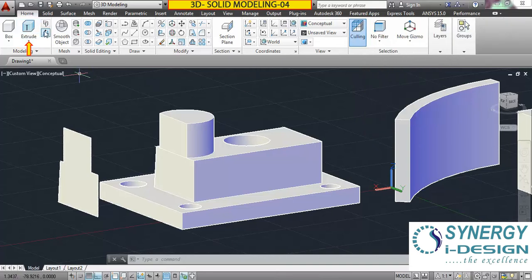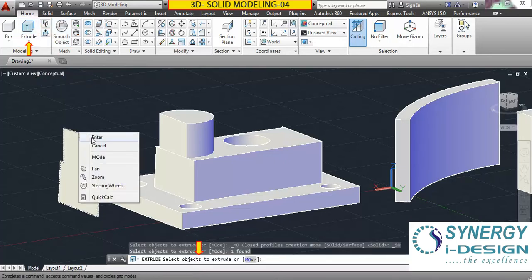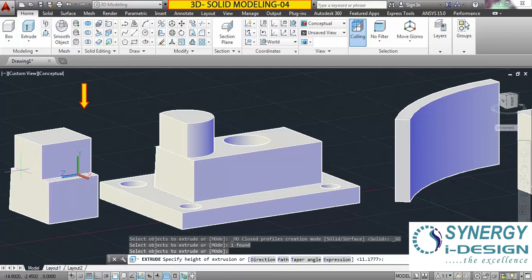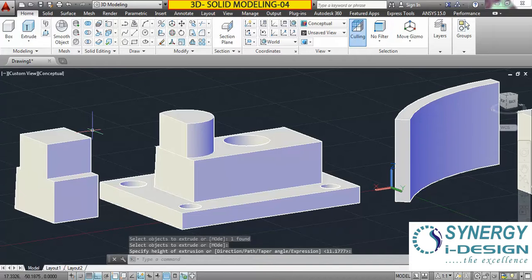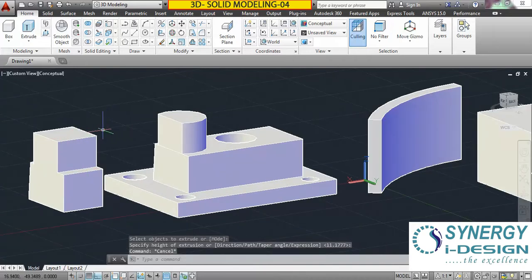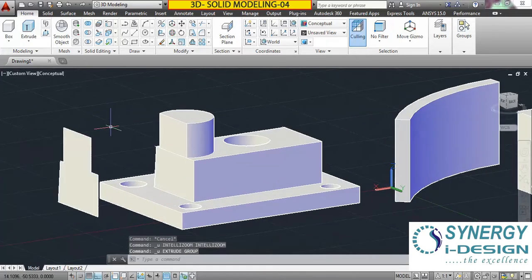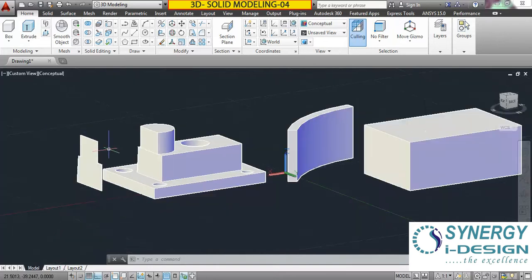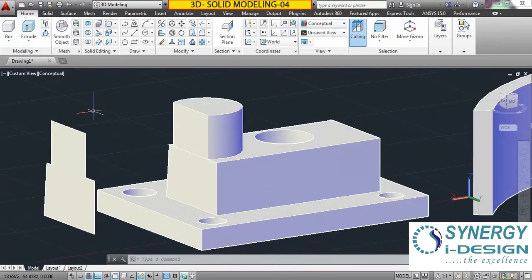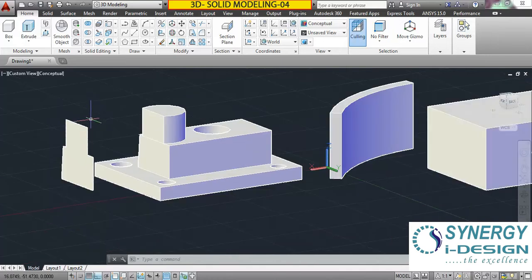like this. Suppose I want to create a solid, then I can create it by using the extrude command, or I can revolve this section, this region. So we can easily say that this copied face works like a region. That is the prerequisite for extrusion and revolve. I'm deleting this created face.